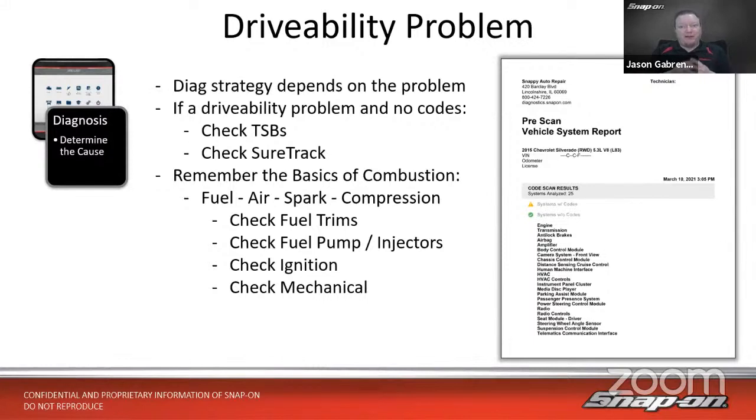And then also, if it's a drivability problem, it's usually a combustion type problem. It's not burning properly. The engine's not operating properly. So remember your basics. Always remember your 4 parts. We need fuel. We need the proper amount of fuel. We need the proper amount of air. We need the proper amount of spark. And then we need the proper amount of compression. So if any of those is off, we will have a drivability problem.